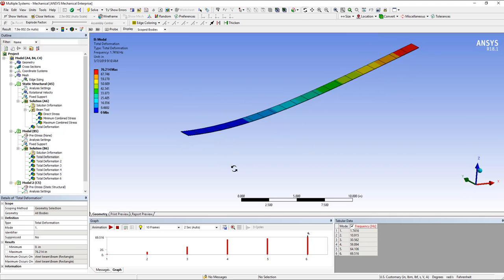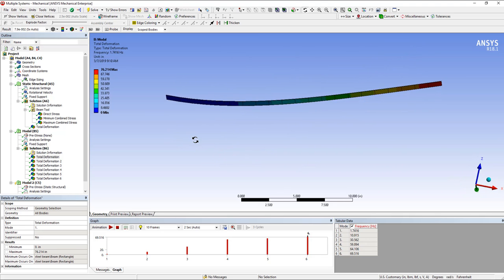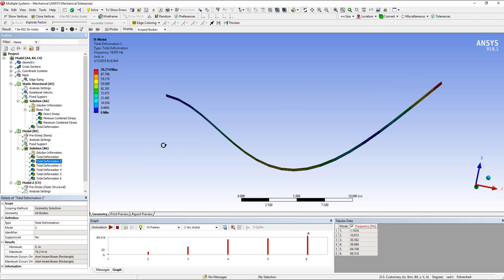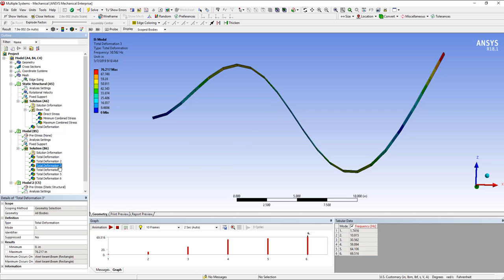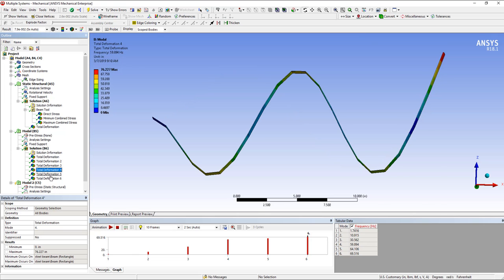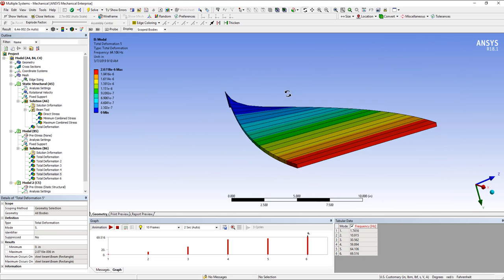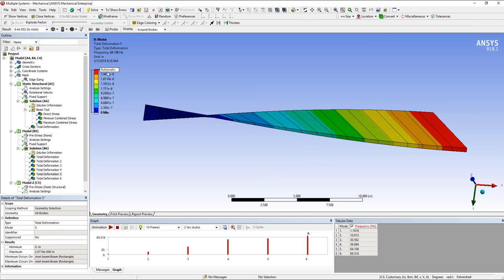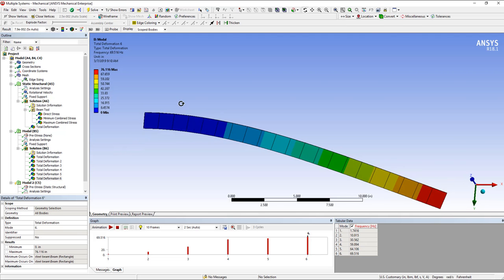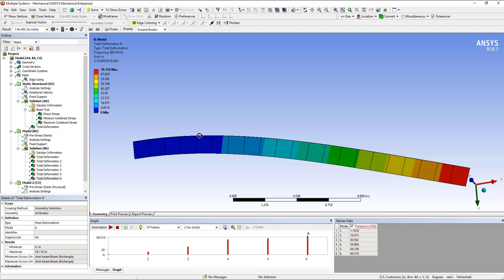That's a more realistic shape that you would expect from a beam, right? It's bending, a cantilever beam. And we can see a second mode, the third mode, and they keep getting more complex. Okay, that's a torsional one. One of the things you'll notice is that the scale of these doesn't make a lot of sense because these are essentially vectors, deformations, eigenvectors, and the frequency is an eigenvalue. They're all over the place as to the magnitudes, but you don't pay attention to that. You're interested in the shape, understanding what's moving and what isn't, and then the frequency.